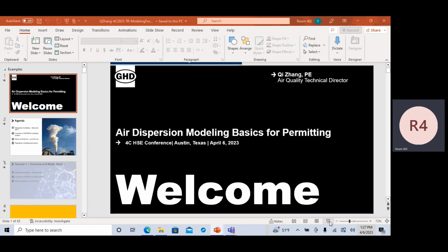And faster running options. For area source, AERMOD actually uses a numerical integration method, so it'll optimize that process. They're calling it optimize, they basically cut some calculation or make the model run faster. Fast all is the same thing; optimize is for area source, and fast is for point and volume source.